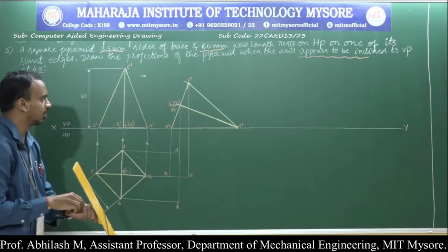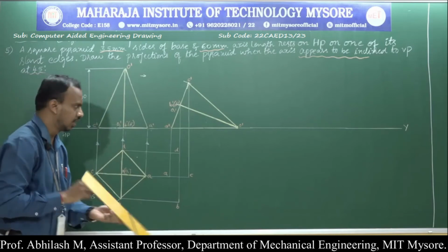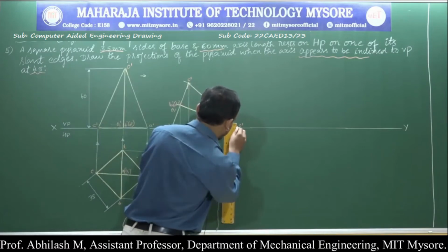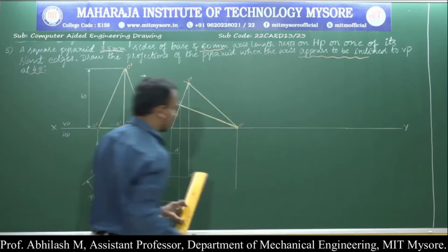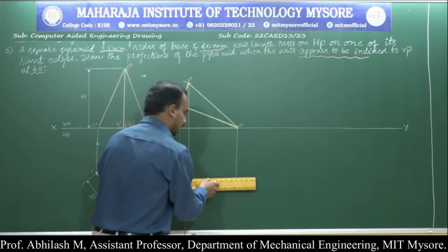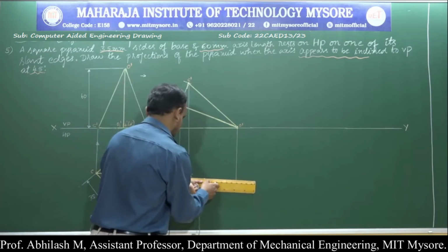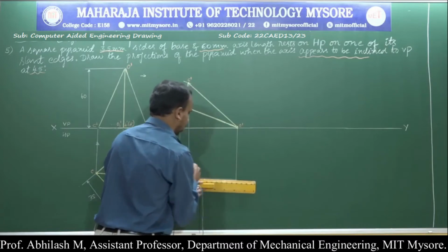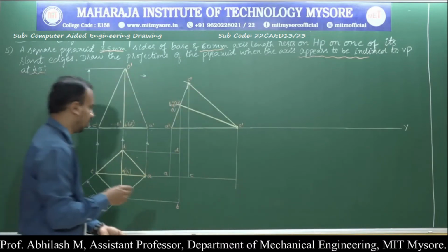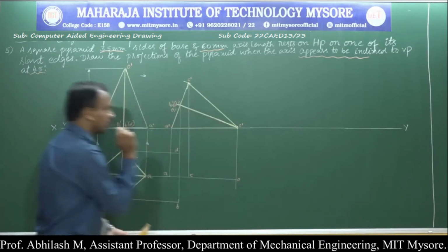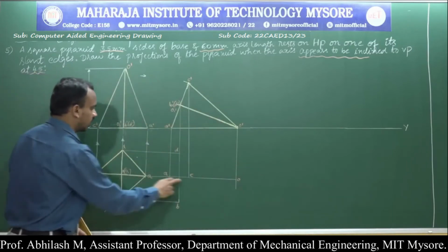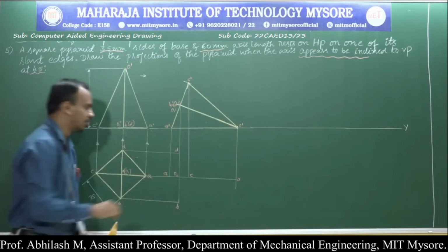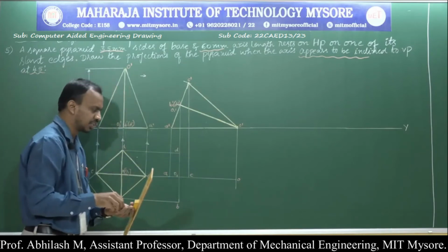Now we are left out to identify the point of O dash, basically O. Just draw the projection line, and O is here at the center. So extend the line. These are all the projection lines, the thin lines that we are supposed to draw. So call the point to be of O. So we are left out with only O1, and O1 is going to meet here. So the point is here. So we have identified all the points correspondingly with the help of the projection lines.